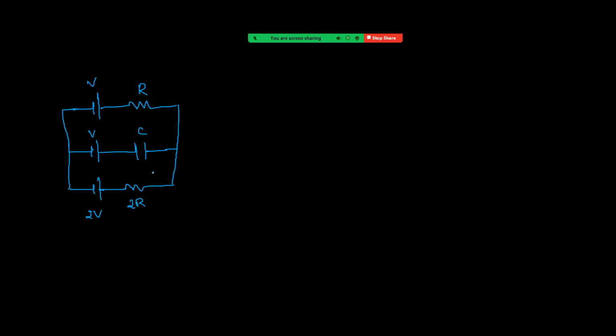In steady state, there is no flow of current in the capacitor branch. So focus on how to calculate the current in the remaining branch. Let us take the current as anti-clockwise. I'm taking Kirchhoff's second law here. If you know it directly, we can write the current. If you don't know, use Kirchhoff's second law. Suppose starting from here, I'm moving anti-clockwise. See carefully.